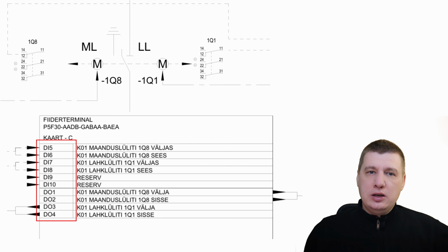Technically, they are highly configurable. You can set the nominal voltage from 24 V DC up to 230 V AC and adjust the bounce filter to prevent chatter from making the relay think a switch is bouncing. You can even set an activation delay of up to 60 seconds if you need to wait for the signal to stabilize.